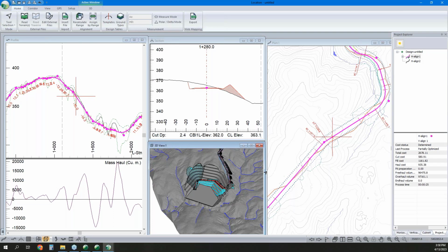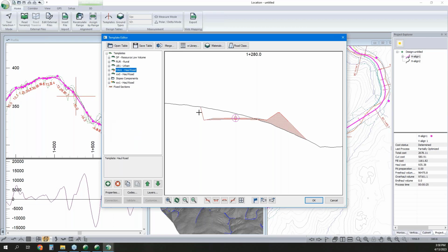Yeah, the volume calculations in location are going to be based off cross sections, so that is where we want to go back into terrain and do it as that tin subtraction to get the total volume of those large projects that aren't really well represented as a center line with cross sections. But you can certainly lean on the functionality of templates to make it really easy to see how you're going to interact with the surrounding terrain and get those limits the way you'd like.